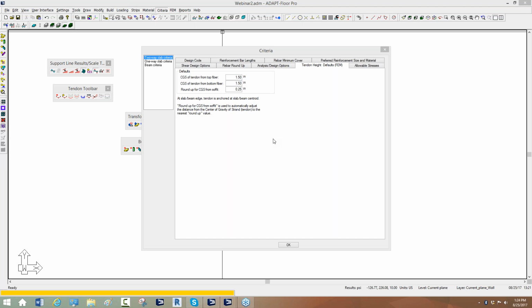So there may be a need for you actually to check the stress for initial without the upper supports, and then check the sustained and total conditions with the upper supports in place. And it just depends on the situation. So thank you for the question, Gustavo.